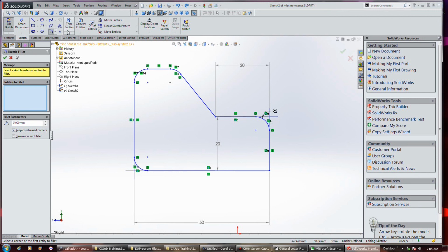But of course, you can go into tangent and change the radius too, like let's say 10. So like, let's make that one 10 and that one 10. Okay, then voila, that's got a radius of 10 applied to it. Again, a lot better than trying to use that continuous arc thing, which is kind of neat, but boy, it's squirrely, and then you have trouble actually dimensioning your parts.